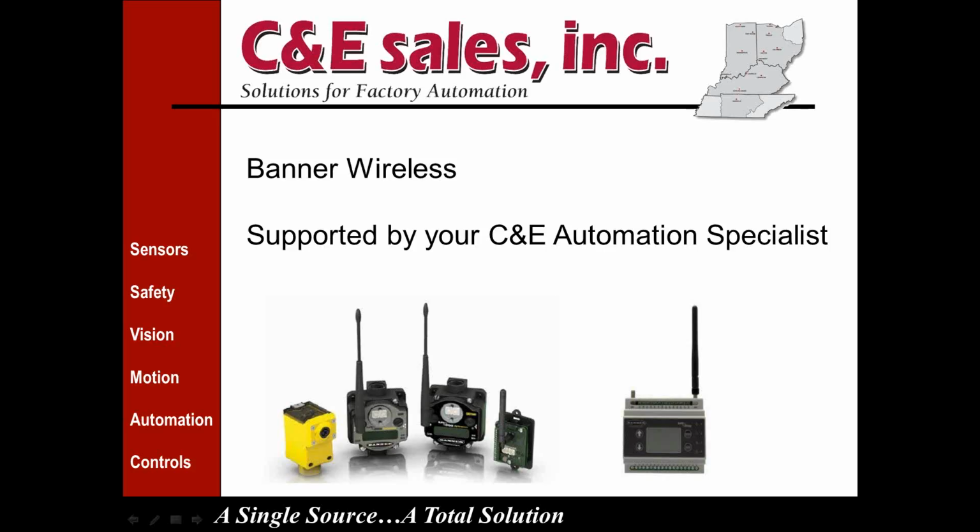And let's see, question here concerning signal strength. How far can the individual nodes be from the gateway and still have good signal integrity? Something else I didn't really go into is antenna selection. Banner also has some other antennas. Most of these come with what we call the rubber duck type antennas. Those typically, at 900 megahertz and 1 watt signal strength, with clear line of sight, you can see across, a mile, and Banner's based in Minnesota, so it's a lot of flat farmland, so they can do up to 6 miles clear line of sight.